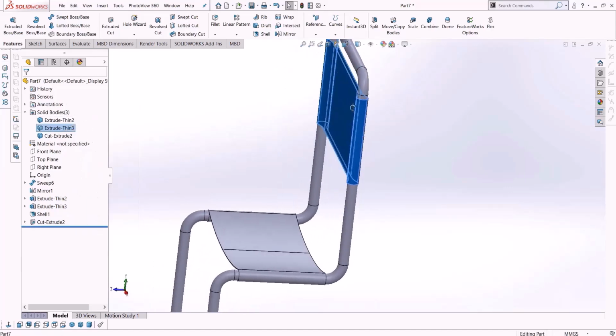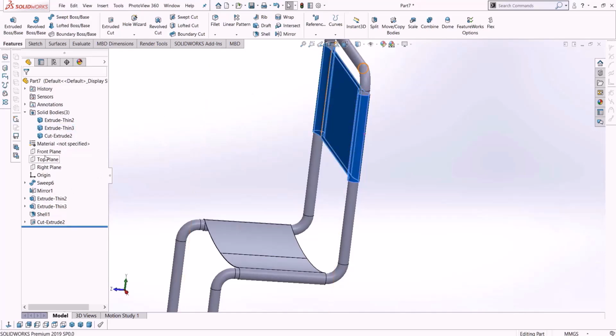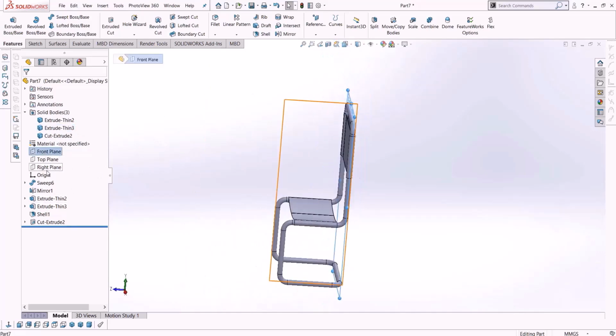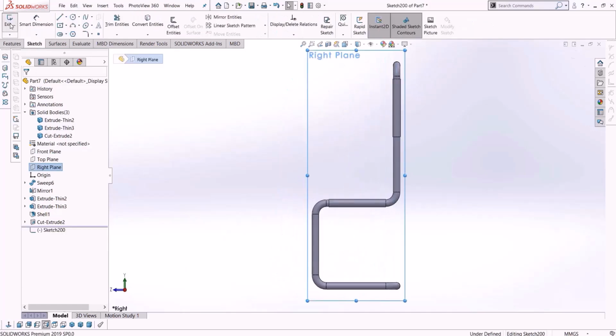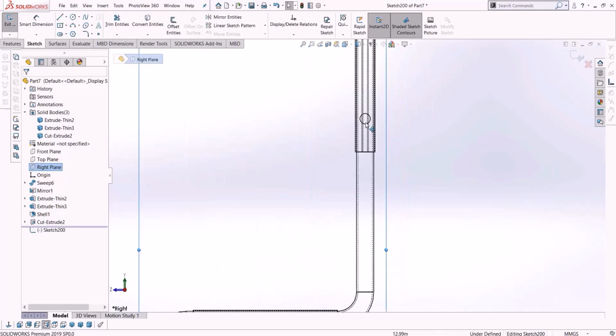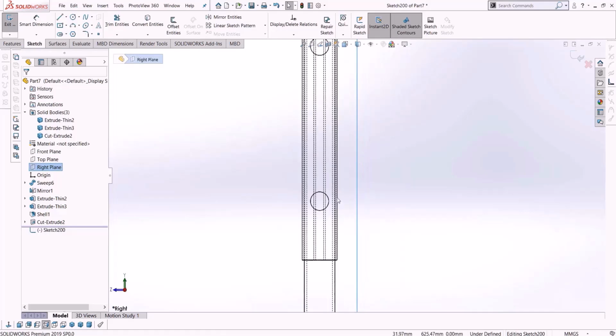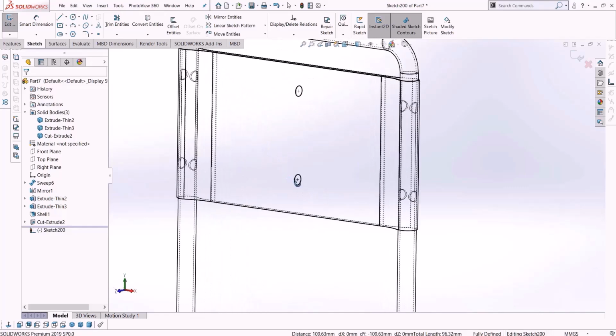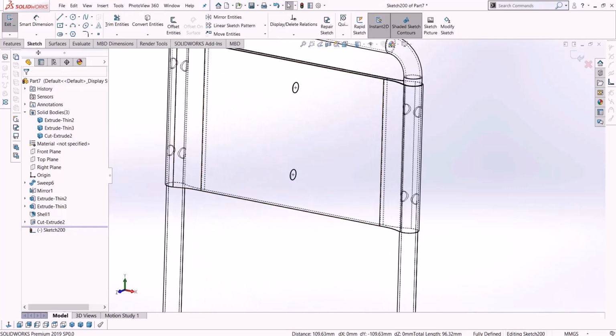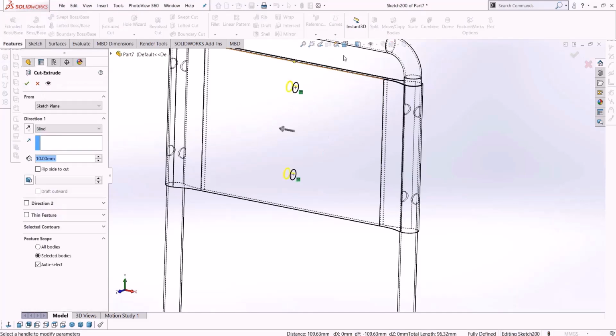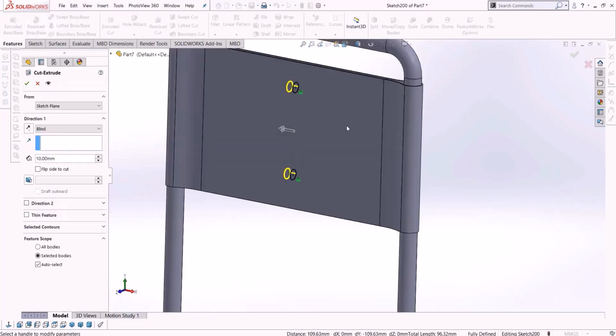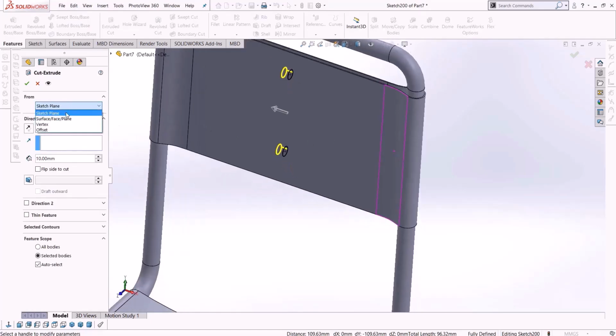This is from the height, and when we click on this spring, it goes back. I will take it out again, come to the right page, and select it again. I went this way so you can see that we can now see the hidden lines, and say that these two circles you see here, I selected them with Control and clicked on Convert to get those two back. But what's the difference? I also want to perform the extrude cut.